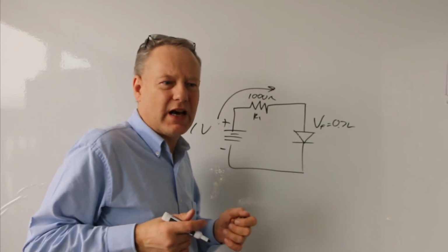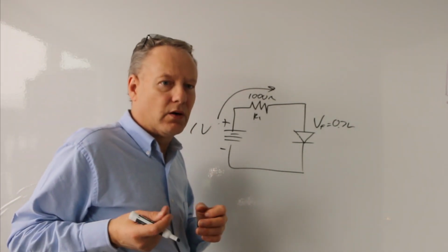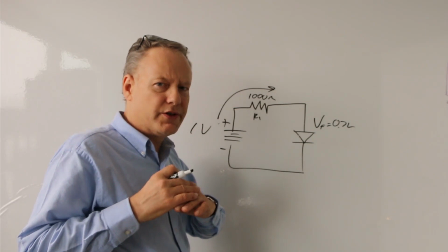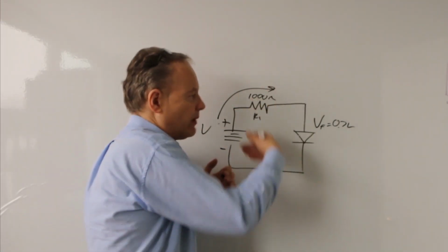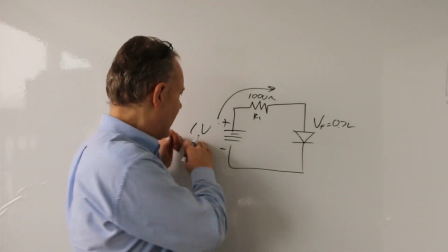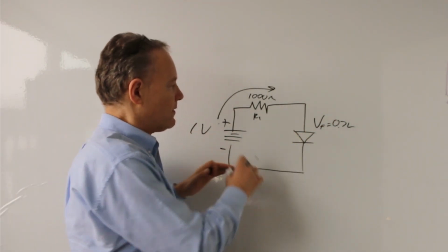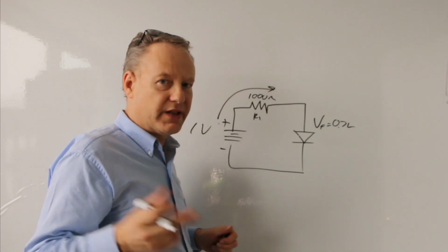When I say open, it's kind of like a door being open, or a switch being closed, which allows current to go through it. So just deal with my terminology. This thing is open, it's allowing current to go through it because it has more than 0.7 volts. So now current's going through it. Now let's take a look at something.